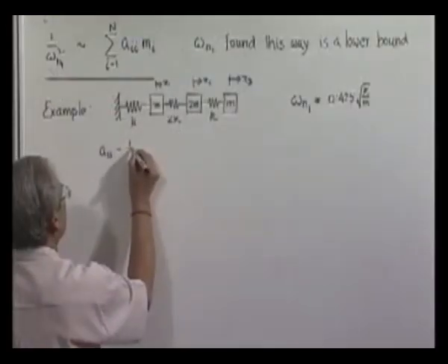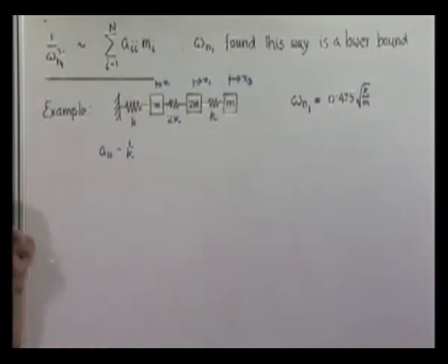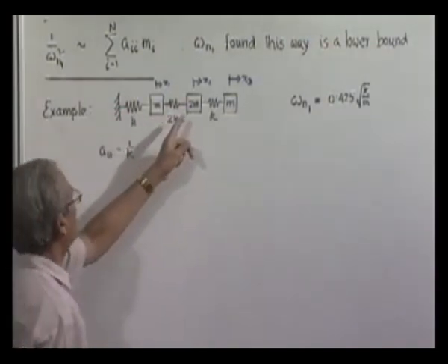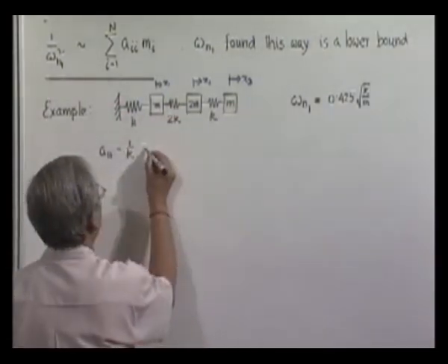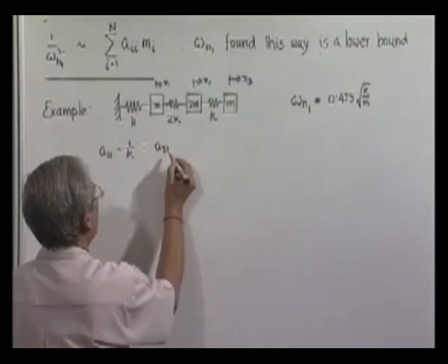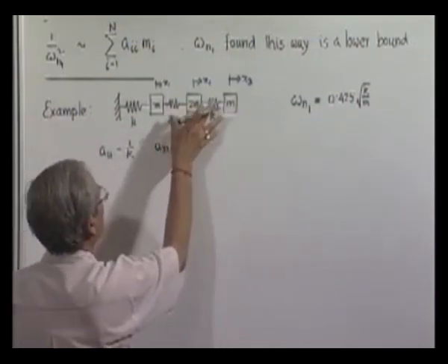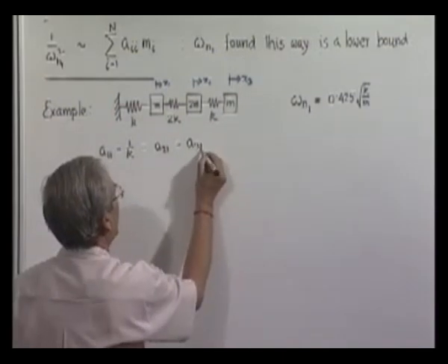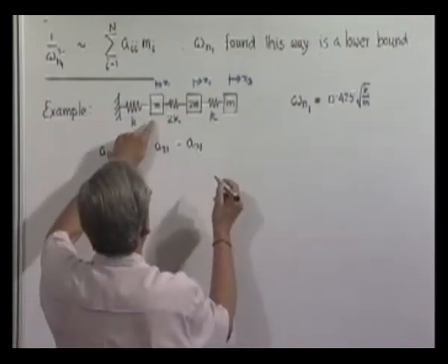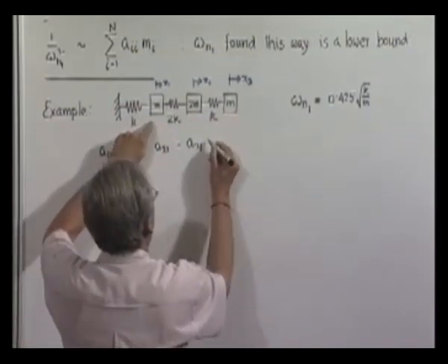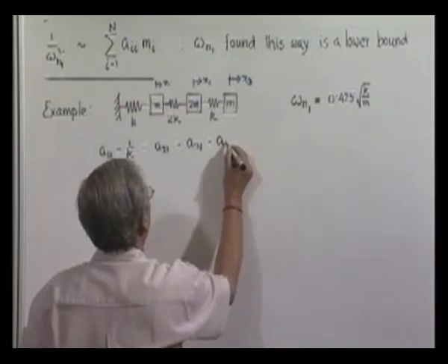So, it is nothing but the stretch of the first spring. So, it is this, and this will also be the deflection at station 2 due to a unit force at 1, because this shifts just like a rigid body. And again we know the deflection here due to unit loads here and here are going to be the same.